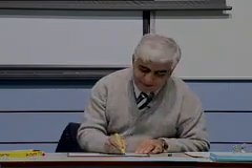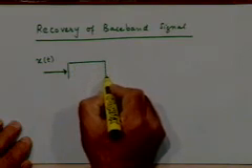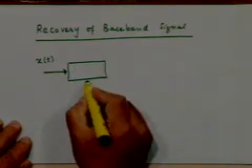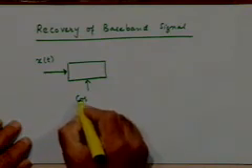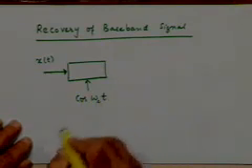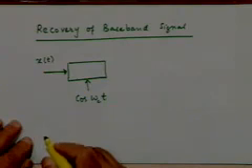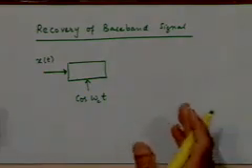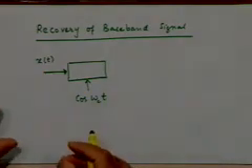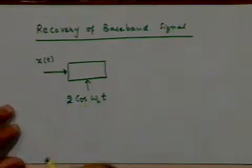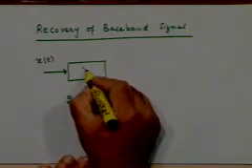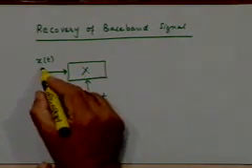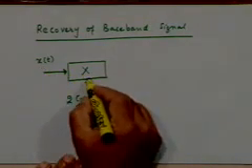The first stage would be, assume that at the receiver we have a replica of the carrier available to us. The carrier frequency is known to us, and we can generate a replica of the carrier. For convenience, let me write 2 cosine omega ct here. Doesn't make any difference. It's a scaling factor. And the received modulated waveform is multiplied with this carrier.